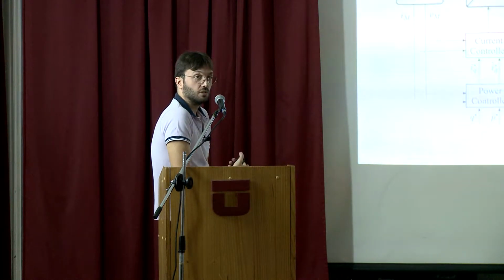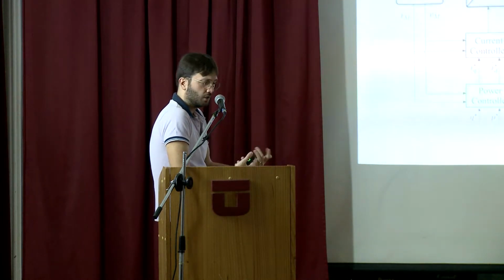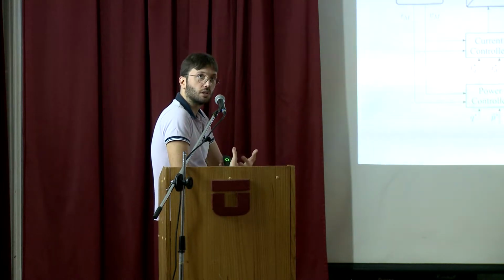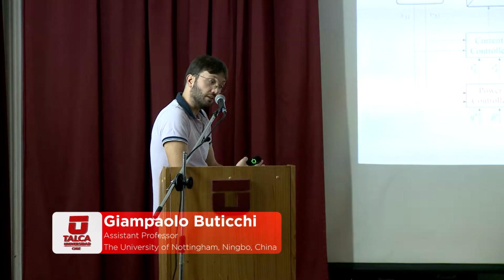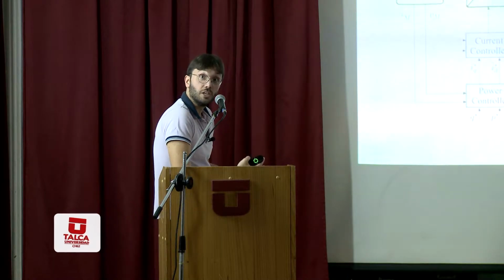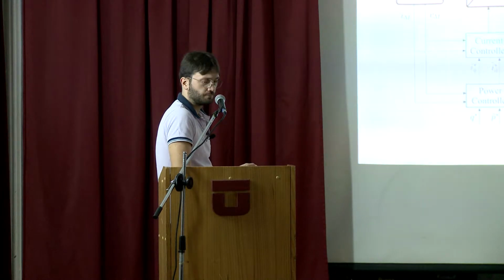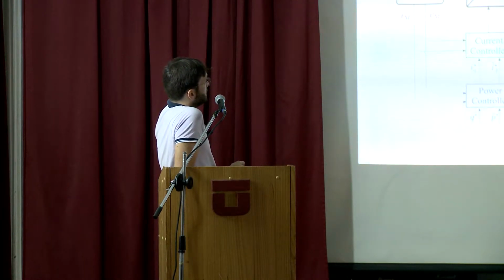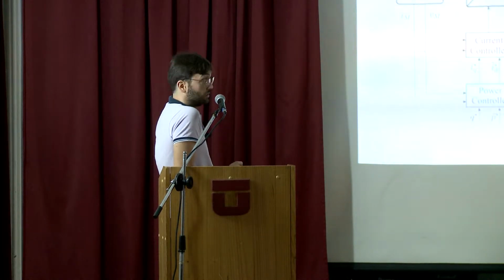Well, in the case of the dual active bridge, we have the possibility to control the power exchange. Dual active bridge is a very nice converter because of the principle of operation by controlling the phase shift. There is a power equation, so we actually get open loop power control, basically. So by changing this phase shift, or anyway the control variable if we have another DC-DC converter, we can transfer power to the low voltage DC link.